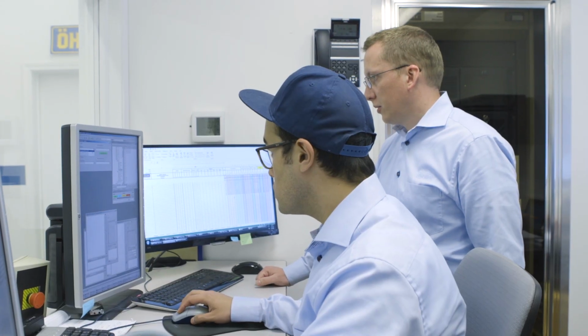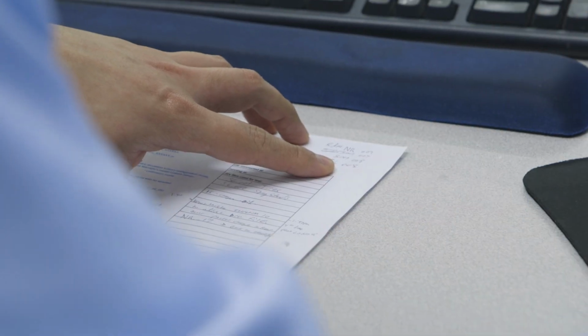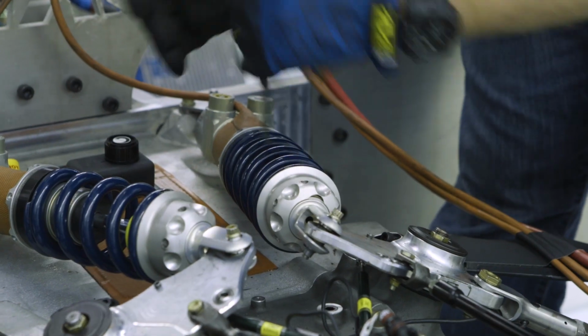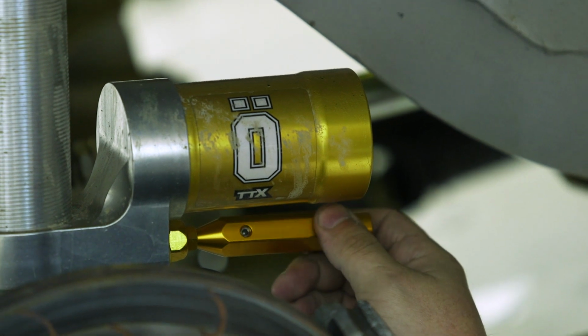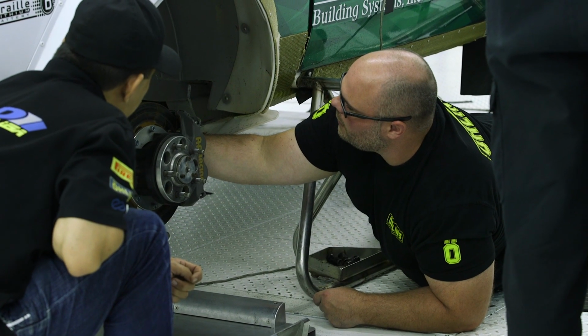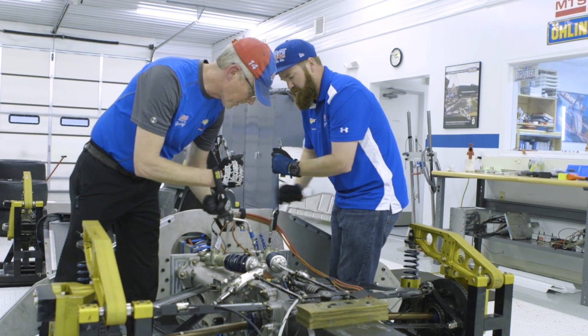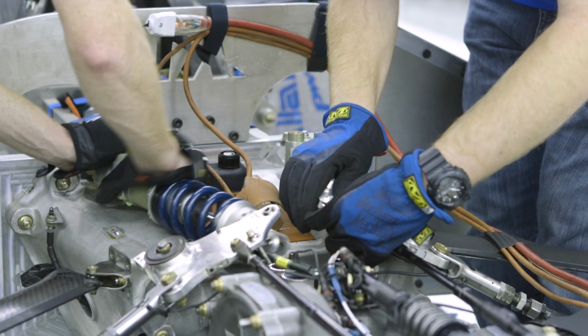With the data measured from the simulation, such as tire load variation, a measurement of mechanical grip, we can accurately help you or your team dial in your vehicle's suspension to ensure that you are getting the best vehicle performance possible. We can typically give you sort of a roadmap of adjustments that will help you know what to do after the test should you be at the track and experience, for example, understeer. You can look at the data and find the adjustment that will most likely fix it.